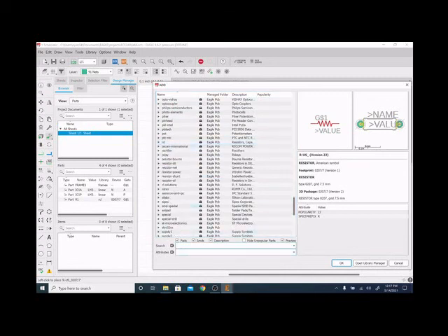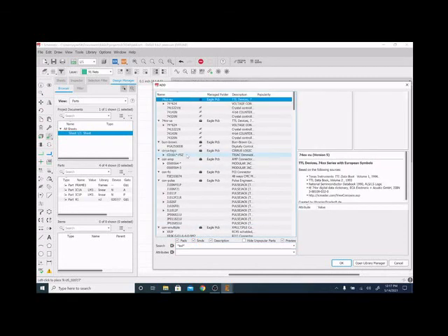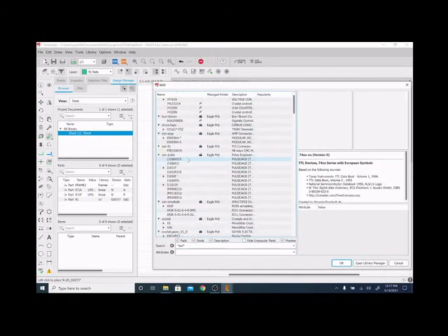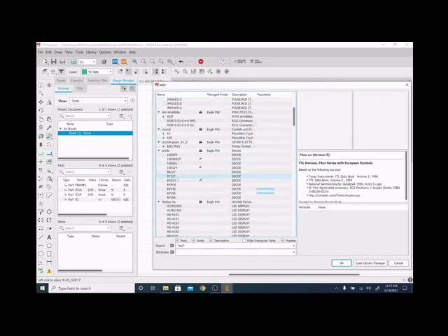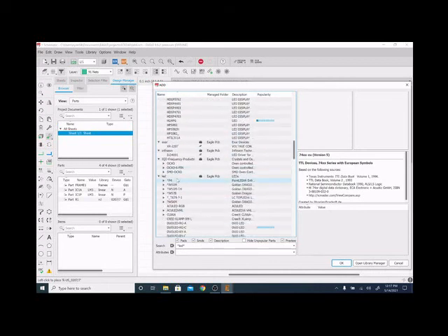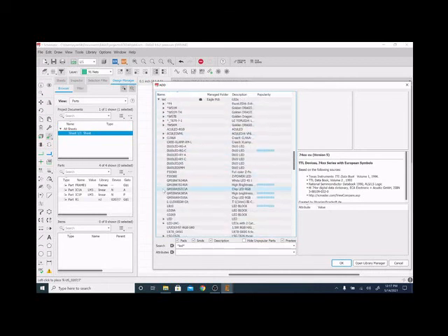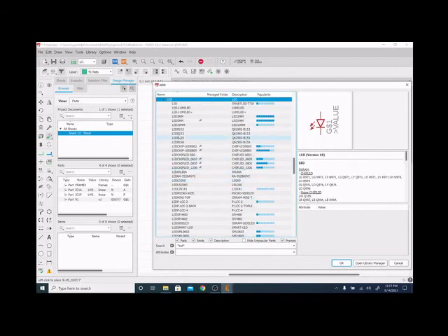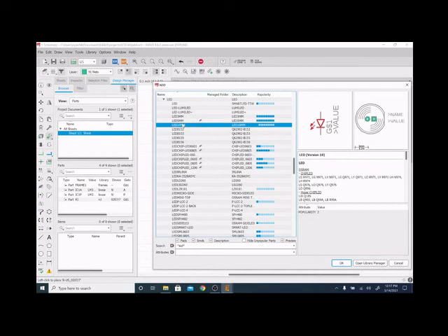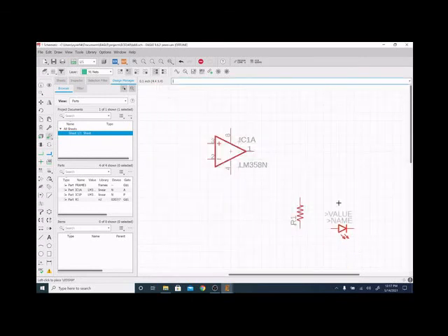Now I'm going to search for LEDs again. So I'm going to do asterisk, LED, asterisk. You can see there's a lot of stuff going on here. I'm going to go down. I know it's a diode. That's not quite right. Here we go, LEDs. That looks a little better. Let's look at this. Aha, here we go. 3mm, 5mm, and 10mm. 10mm are pretty massive. 5mm usually work pretty well. So we know that we need 2 of those, and we want the cathode facing down. So I'm going to put one and the other one, just like that.